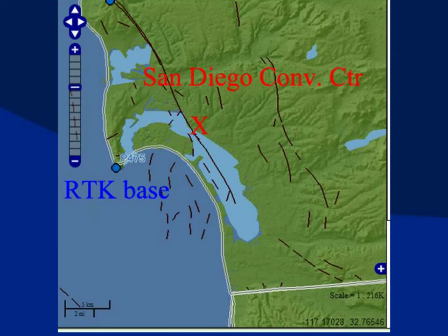But again, we just got out. We walked over from the convention center out in open park, turned on the RTK receiver, had an iPad right there, typed in the credentials that I posted before, the IP address, port number, login, password, picked this particular base, and I'd say within 15 seconds we were getting a fixed solution. It was pretty slick, and we had it running in ArcGIS Collector, and I forget what else we had down there for data collection software. So this is an example of an RTK network.